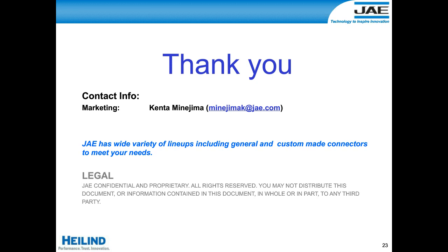Yeah, so that is absolutely true. Obviously, Type-C connectors are probably maybe double or even more the price of a traditional micro USB connector, and that's based strictly on the fact that it has so many more pins and is so much more difficult to manufacture. There are new types of products coming online shortly that are going to have some of the actual pins pulled out of the Type-C connector. So in cases where you only need power or you only need to support slow speed data transfer, you'll have a slightly less expensive connector with some of those pins pulled out.